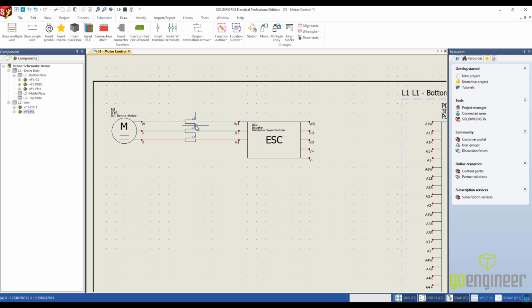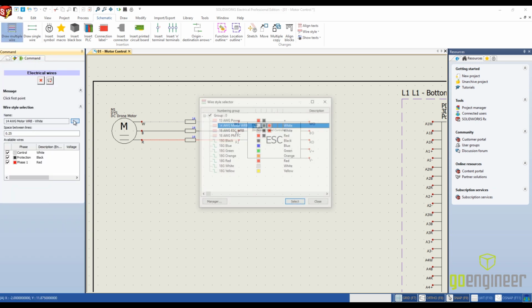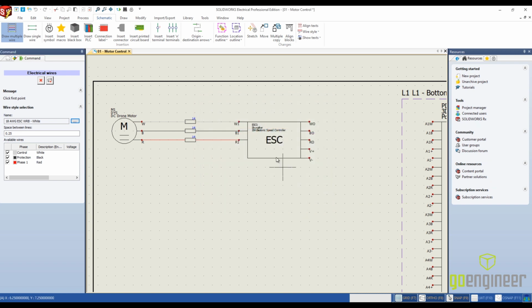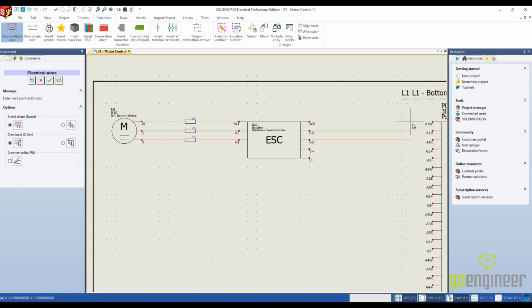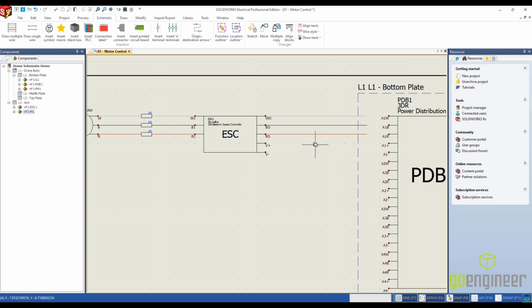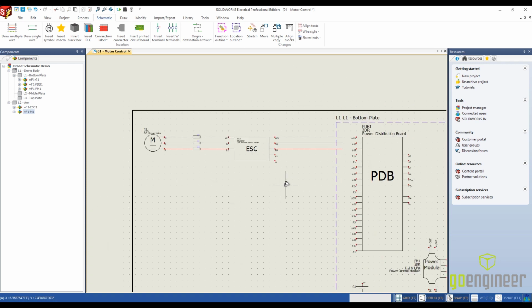And then we'll next add our wires that go to the distribution board. So I'm going to grab some 18 gauge wire for this, and again it's just a white, black, red. So I'm going to bring this over here and not quite connect it right now, because I'm going to create a macro, because I need to make 3 more of these setups. So I'll show you how to create a macro here shortly.